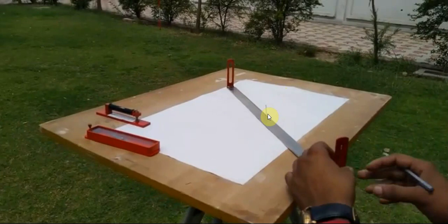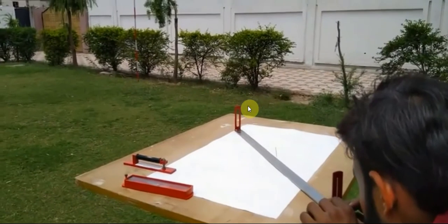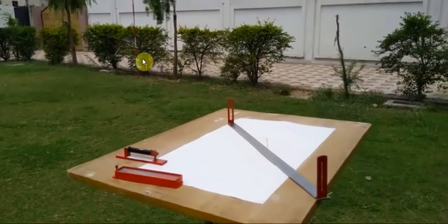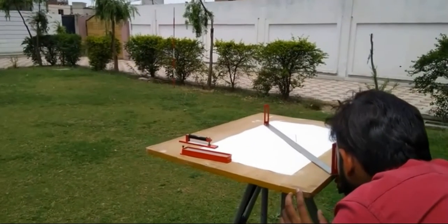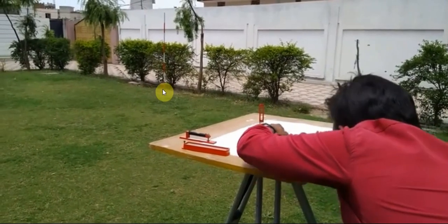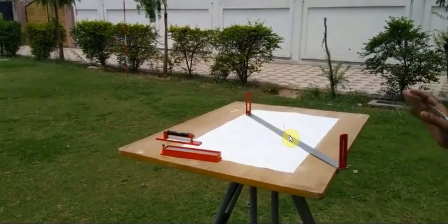Now I'll put a pin on point O and sight through the sighting vane, through this narrow slit, and bisect the ranging rod such that this crosshair, or this thin hair, bisects the ranging rod. So I will rotate the alidade, and when I'm rotating it, I should make sure that the alidade is passing through point O, and then I will draw the ray.